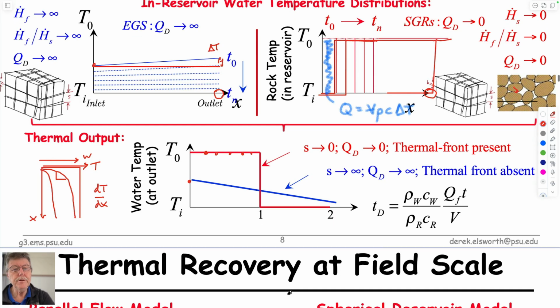And then once it gets depleted, then the gradient of dT/dx is progressively smaller and smaller at this interface, and that's what controls exactly the heat flow out into this. So as time goes on, it gets a shallower and shallower gradient, and so the difference between temperature inlet and outlet gets smaller and smaller because it gets less and less efficient.